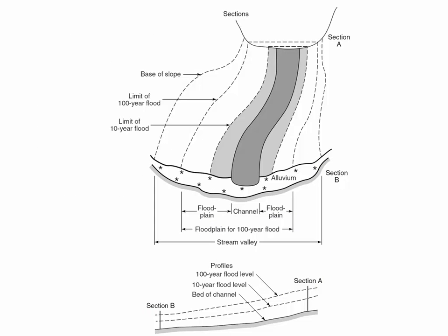So it's a floodplain that we're in. And you can see that the floodplain can be broken into different parts. In this diagram, they're showing you where the stream usually is. This is the typical channel for the stream, and then when you have a 10-year storm, you can delineate how high the water level gets and therefore how much of the land is covered by water during a 10-year storm. You can see what the limits of the water are during a 100-year storm, and so on.